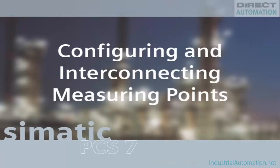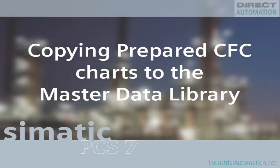In this sequence, we're going to show you how you can implement your own templates, that is, sample solutions for specific process automation functions, in SIMATIC PCS 7, as a basis for carrying out the application engineering of your plant. In addition to these sample solutions, which are created in the form of CFC charts, a sequential control program in the form of an SFC chart is also used. The SIMATIC PCS 7 library comes with standard templates, for example for motors, valves, and controllers. For the purposes of this exercise, we will make use of a customized library to show you how you can use your own company-specific templates.